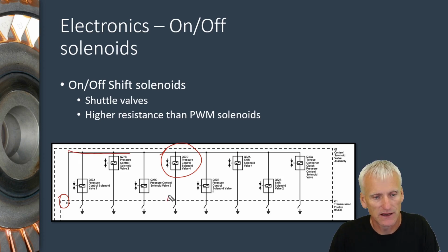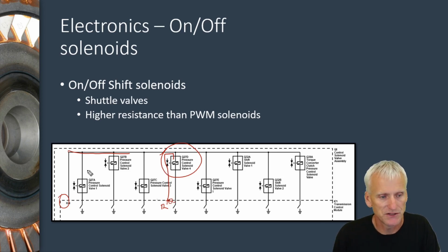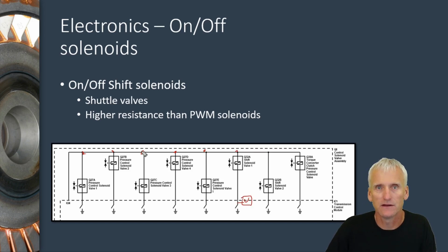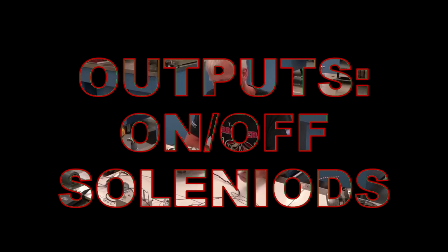You'll actually have a dedicated power and ground for each solenoid, because they'll do a comparison in there to calculate the current flow. So usually when you see a bunch of solenoids banked together off the same power feed, like you are in the 6L80, where they're all kind of tied into the same power feed, they're not going to be monitoring current flow through it, but they still can do that voltage check right there just before the transistor.